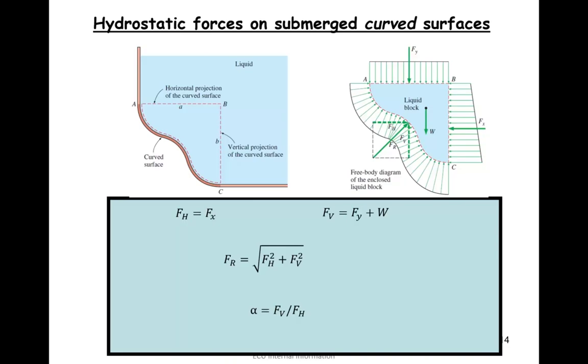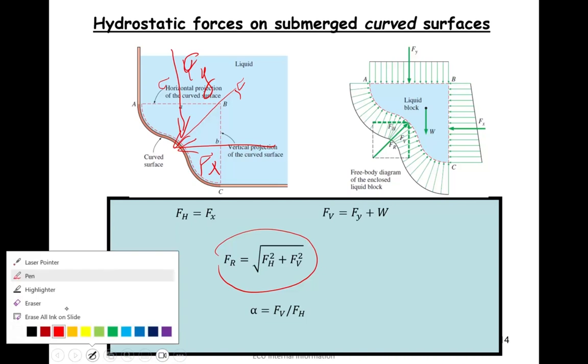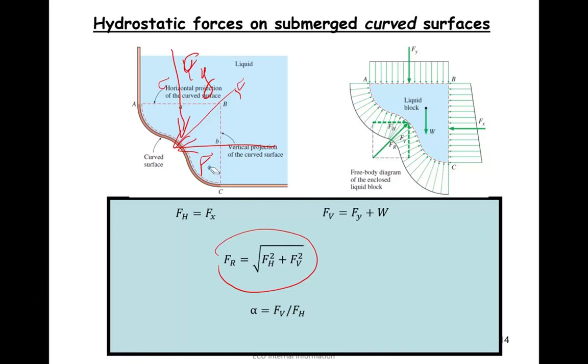Say, for example, fluid is in there, a force acting on here, then you need to split it into Fx and Fy, which is this direction, yeah? And then through that you can work out what the resultant F is. This is the simplest and easiest way to work on curved surfaces.